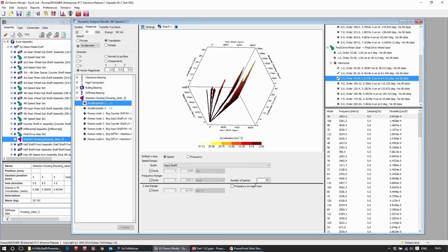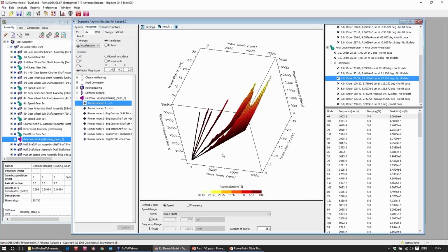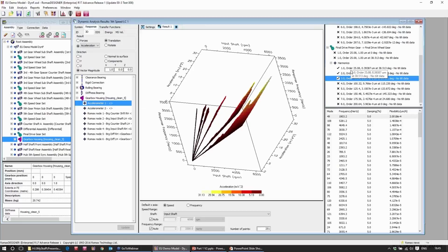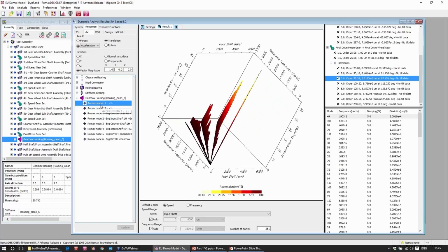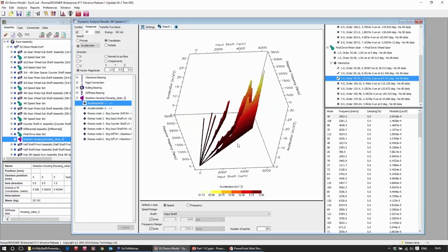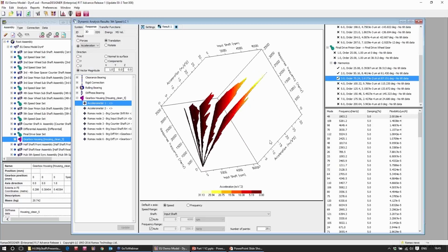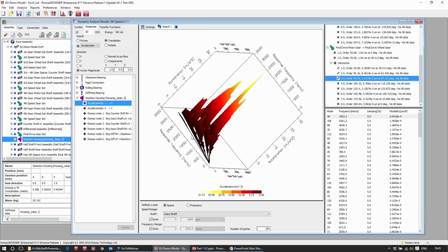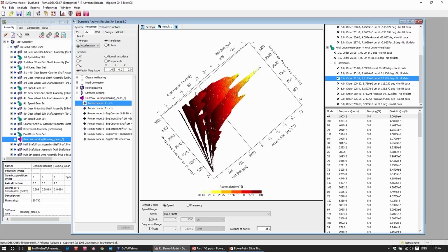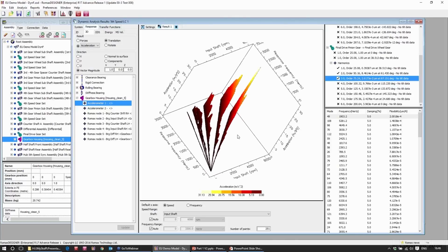And so we can see here, and if we get a little bigger, we can see all of those. I've selected the first three harmonics of transmission error for both the final drive and the fifth speed gear mesh, and we can see how the response at this particular location, one of these accelerometer locations, is varying both with speed and with frequency, and we can use this to identify where particular orders of the gears interact with particular resonances in the system, leading to problems.